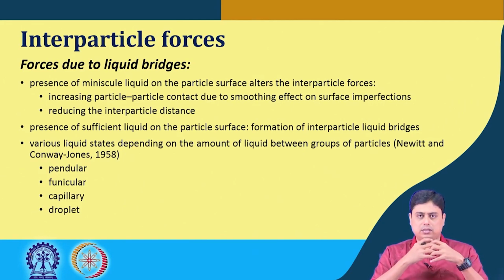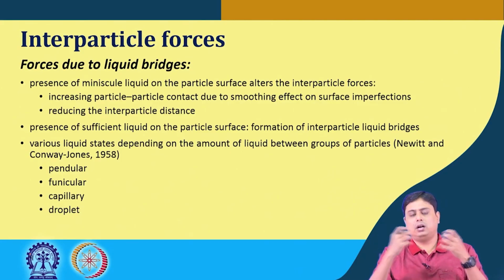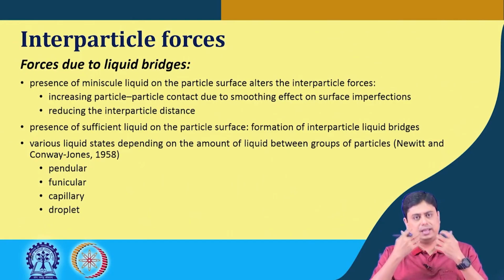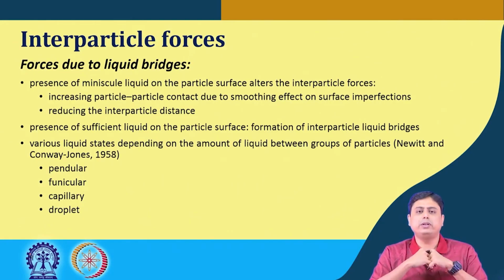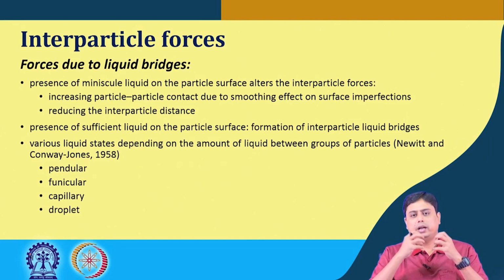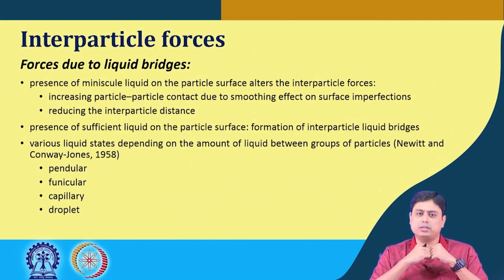But if we have a sufficient amount of liquid on the particle surface, then the magnitude of the earlier discussed forces is not taken into further consideration. It becomes insignificant. Then what happens? It forms the liquid bridges. Various states of these liquid bridges have been identified by researchers, and those have been categorized based on the saturation of the interparticle pores by the liquid phase.